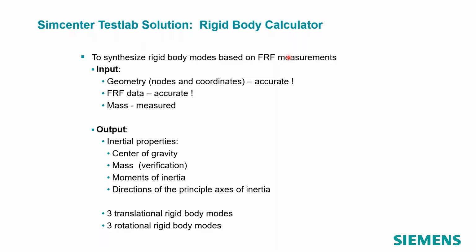If you're not rich enough to have all those accelerometers, you would use dummy masses that weigh the same as your accelerometers, and swap the dummy masses with the accelerometers as you rove. After you calculate the modes, you would use modification prediction to remove the weight of the accelerometers or the dummy masses. This is more important for light structures.